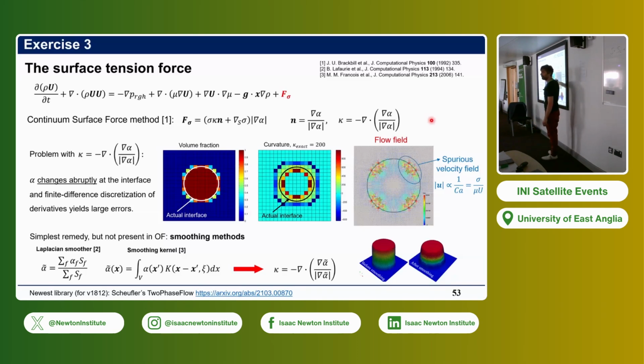That's a big difference, a factor of 2. But you also have these other cells farther from the circular interface where the norm of the gradient of alpha is still non-zero, so you need the surface tension calculated there. But the surface tension is totally nonsense. You get -600 here, +800 inside. So what happens here?